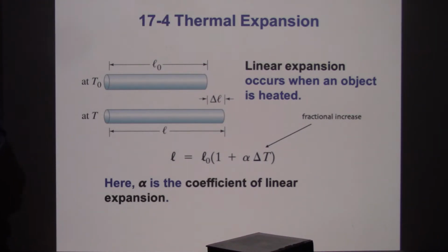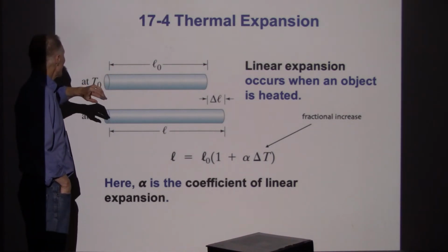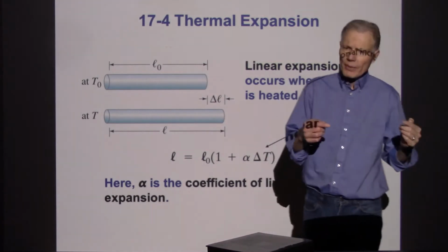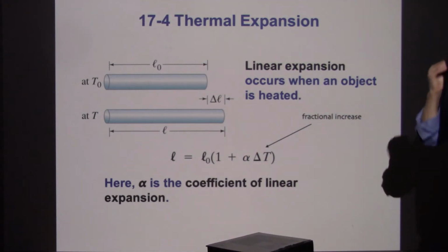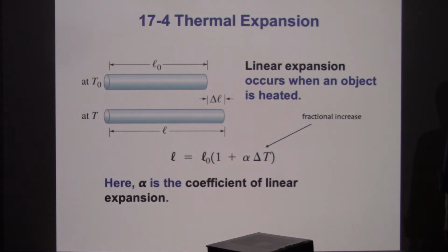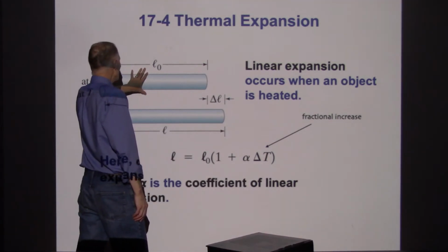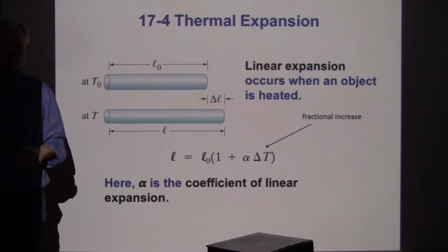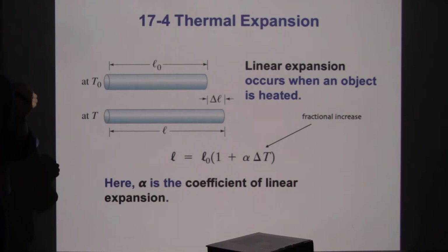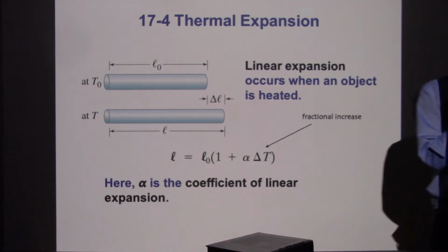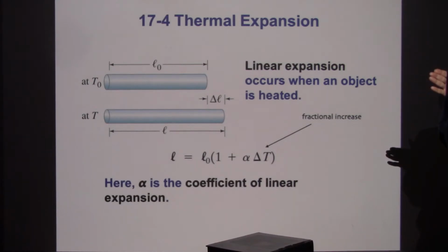All right, we're going to move on to a different topic here. We're going to move on to thermal expansion. Thermal expansion says when the temperature goes up, that indicates more kinetic energy within the material. Let's say this is a piece of steel or maybe a piece of aluminum, some metal structure. As the temperature goes up, that indicates more energy is present in those molecules, and what we find is more vibrational energy of the nuclei actually leads to a larger separation between them.